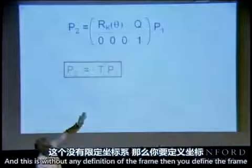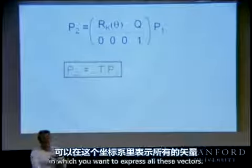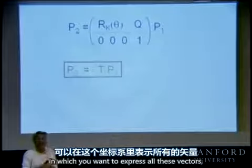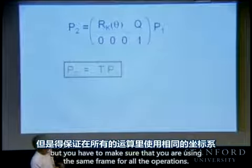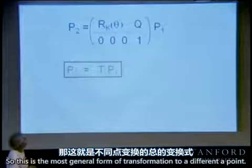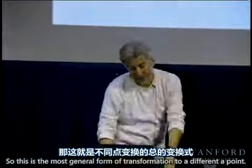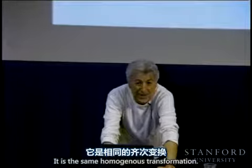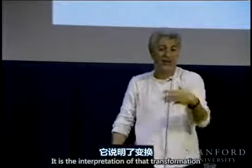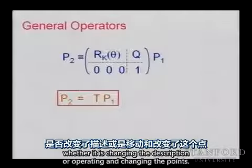And this is without any definition of the frame. Then you define the frame in which you want to express all these vectors, but you have to make sure that you are using the same frame for all the operations. So this is the most general form of transformation between two different points. It is the same homogeneous transformation. It is the interpretation of that transformation, whether it is changing the description or operating and changing the points.